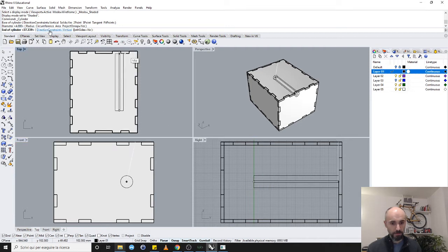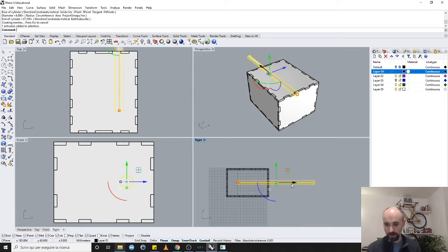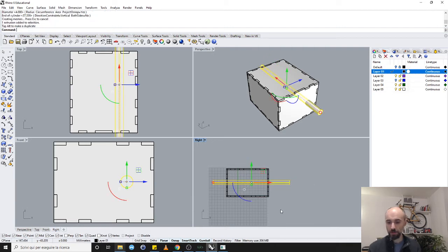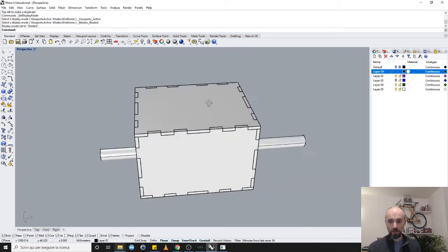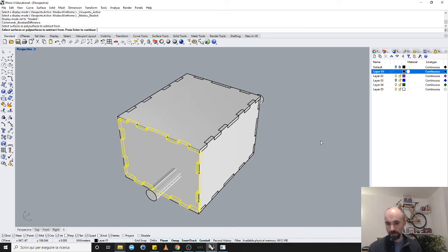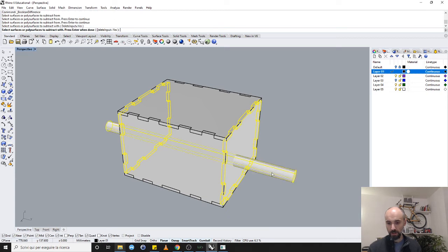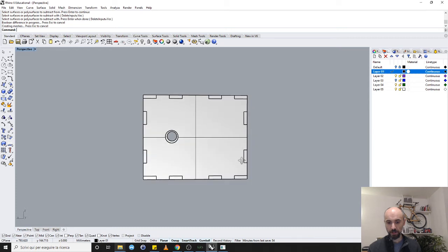make a cylinder, have the cylinder go through the object where we want it, with the dimension we want, of course. At the moment I just draw it a bit randomly, and do a Boolean difference. So let's have it like this here as well. Okay, so if I do a difference between these two parts and my cylinder, of course, I get a hole that goes exactly through the entire thing.